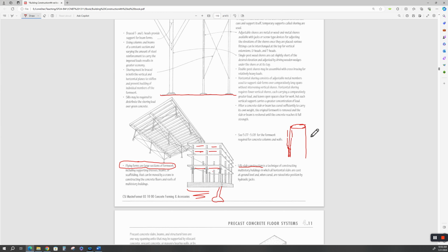And sometimes we do it backwards, like for a lift station in the ground, for sewage to go in. You put pumps in. You'll come up here on the earth, and you'll pour your first box, your first wall for your box. So you got this box, okay?